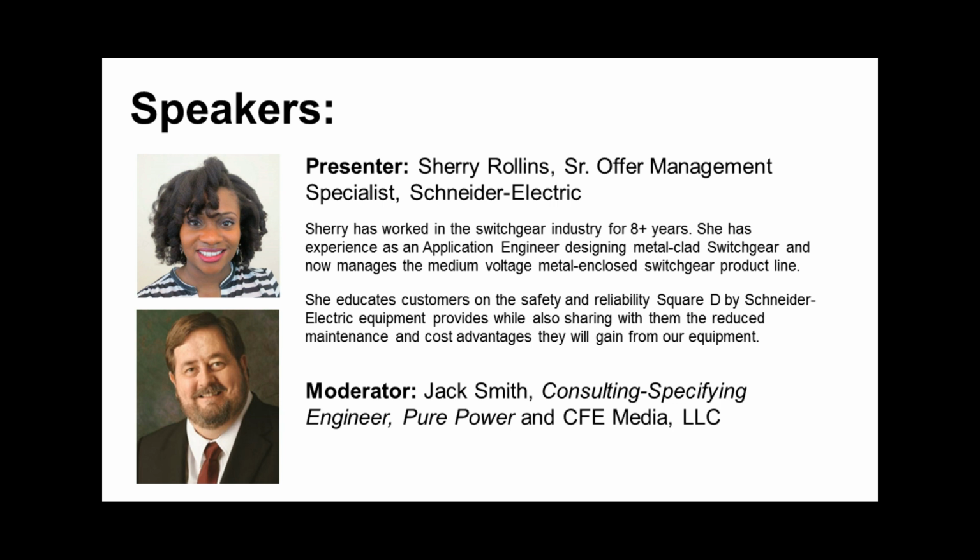And fixed enables certain sealed technologies that are just not available in withdrawable switchgear. With withdrawable switchgear, the reason it tends to be air insulated is because you have to get the breaker out. So there's really no way to hermetically seal the breaker and the bus bars to protect them from the environment, or no way to innovate or encapsulate that entire system to make it safe in any other aspect. So there are some limitations once you start requiring withdrawable switchgear. So to summarize, smaller, less expensive, and some improved safety aspects is one reason to consider fixed-mounted switchgear.